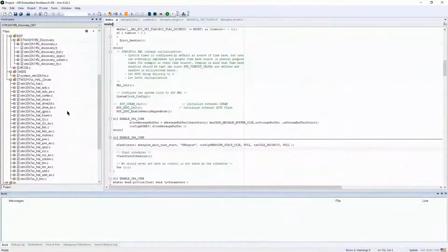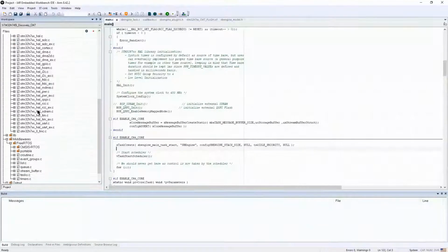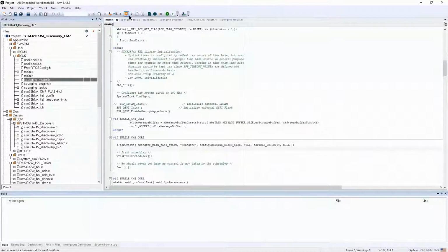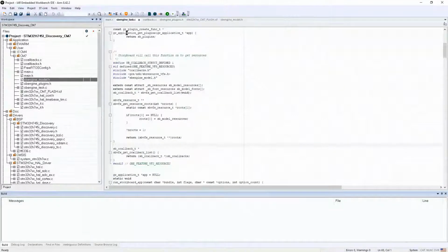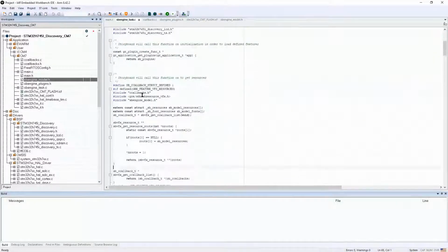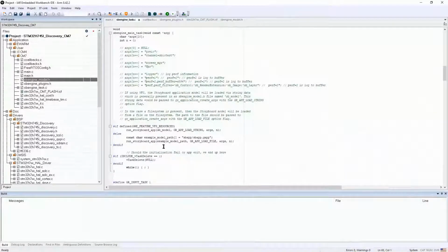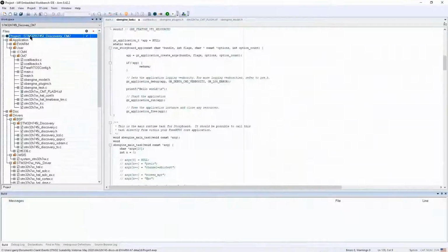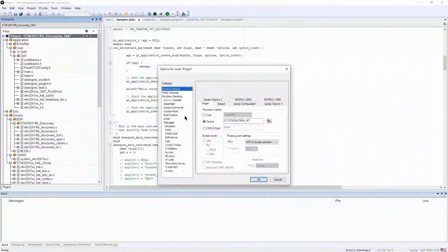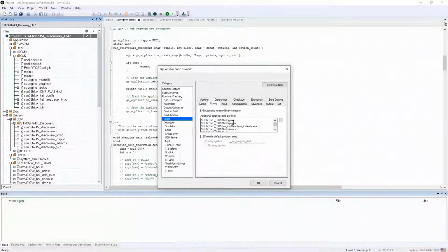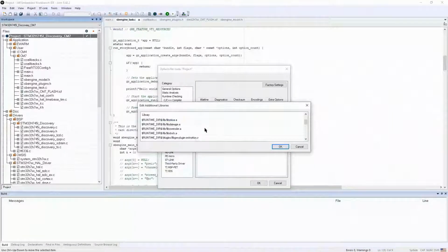And you see here that we've pulled in a whole bunch of drivers and HALs from the standard STM32 Cube. In terms of Storyboard integration, we have a file here called the SB Engine task file that we give you a template for. And again this is very simple. We have the main task, which is literally going to launch the application to kickstart Storyboard, and this is going to be loading up, in this case, Storyboard libraries, which are added in the form of static libraries. Here we have a whole bunch of them. These are very much the constituent parts of Storyboard. Everything is a library and a plugin. So if you're not using a particular feature or a library, then you can remove it to reduce flash space.